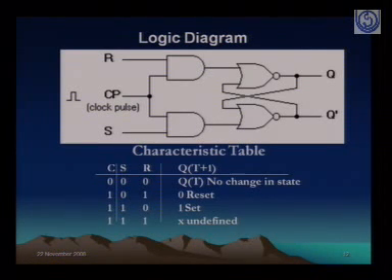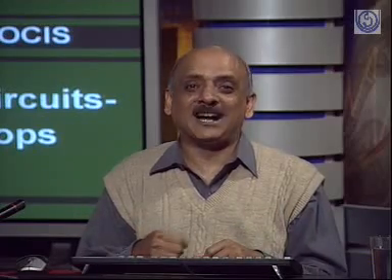We don't know about this particular state. So for this particular flip-flop, what we have defined, the SR clocked flip-flop, if both of these values go to 1 and 1, the state is not defined. In fact, it is then our responsibility, if we are using this particular flip-flop for designing circuits, to make sure that the 1, 1 state doesn't occur. Because if that state occurs, we don't know what state this flip-flop will be in after that.